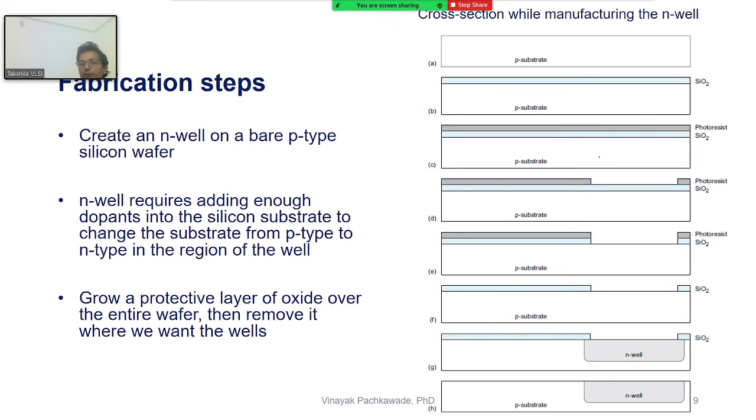Now you got to also have a good understanding about, although these steps are of the manufacturer, things are going to be done in the foundry when the chip is sent for fabrication, but you got to understand how things are done at that end, because oftentimes you have to be compliant with the foundry rules. When the technology comes to you, library comes to you, you have to obey the rules and regulations of that technology. You cannot violate. That's why we will also learn in detail DRC, design rule checks and all that.